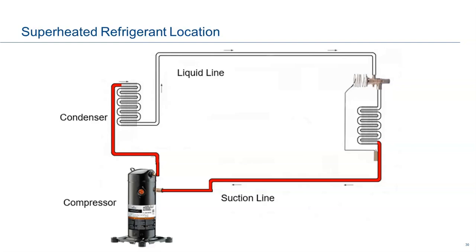I want you to take a temperature reading right here, 6 inches down the discharge line, leaving the compressor. We're not calculating superheat there, but we want to calculate the temperature 6 inches down, leaving the compressor on our discharge line. And the reason for that, we never want to be higher than 225. All of our semi-hermetic compressors are like that, and 98% of our scrolls, okay?